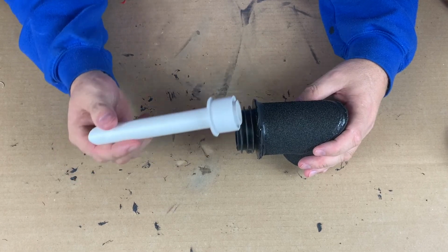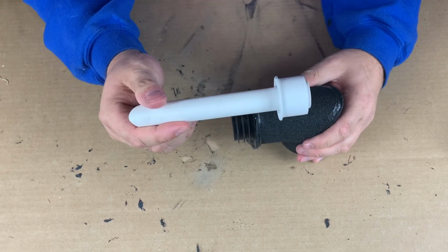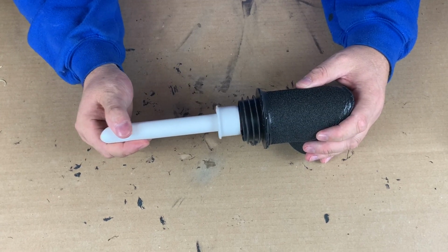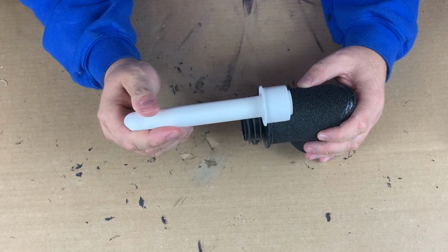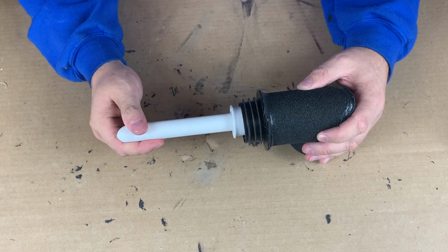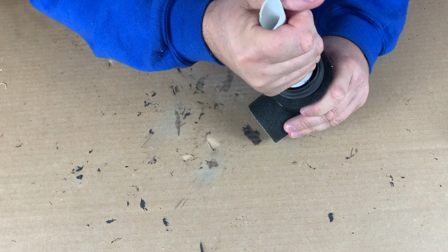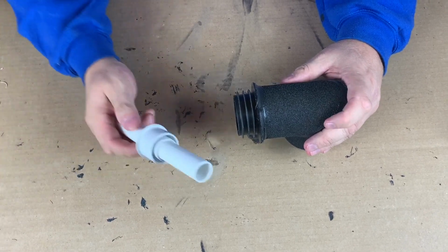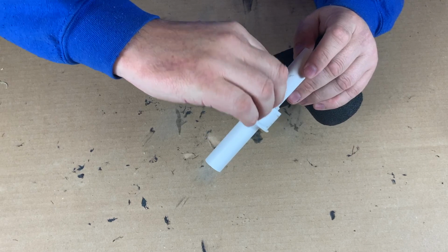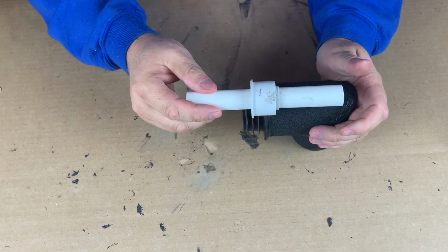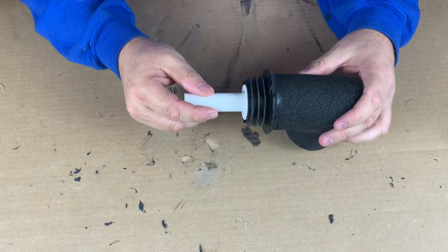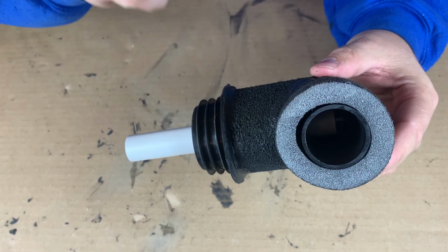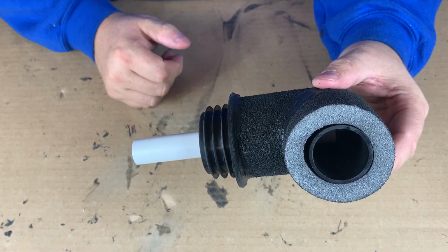So some manufacturers are stating we can use an overflow pipe through the fabric of the building and then terminate it inside to 32mm. What you'd use then is a reducer, 21.5 to 32, and that will then go into the 32mm socket, making a perfect seal. What I've also done, a little tip, is if you take the burr off that stops the pipe and extend the pipe all the way through, that then allows the water to run faster and keep the heat and get to the bottom and terminate faster.